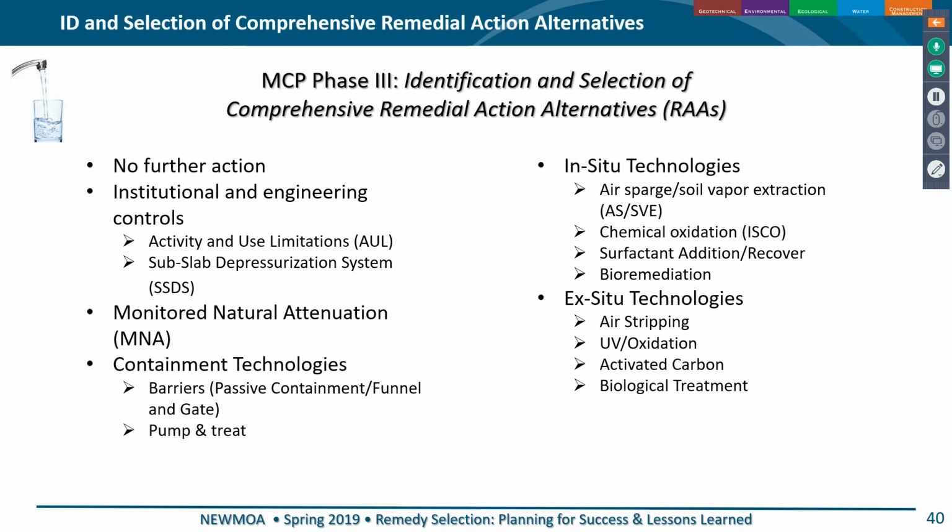We have to review if there's any additional technologies that we should look at now that the pressure's off, now that the plume is contained and not going to this drinking water source. And so due to the nature of the hydrogeology as well as the contaminants, certain things dropped out right away. We weren't going to be doing any sort of barriers because it would require excavating hundreds of feet of bedrock. Similarly, injecting things like air, chemicals, surfactants, all of that stuff made us a little leery because of the potential for uncontrolled pathways due to interconnected and the whole nature of fractures.